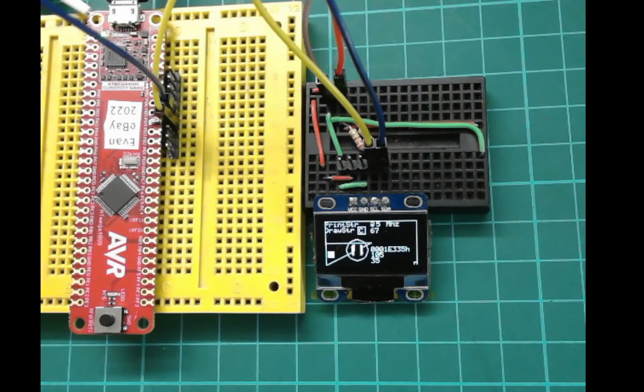So in summary, what we've got is an AVR DX chip, software TWI, I2C. To me, they're the same. I've got 2 wires with pull-ups into my GLCD, and I'm now running that back at 20 megahertz. So extremely simple. From that, you can build your own solutions, and there are many different GLCD drivers you can now use if you're using the software SPI, software TWI or I2C option. Let me just go back to my slides to make sure I've not missed any messages.